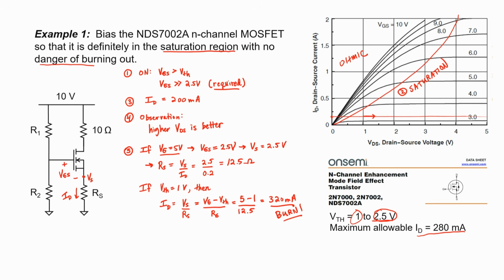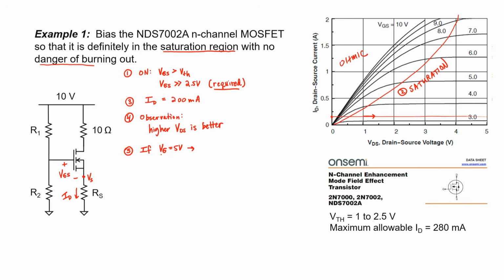Well, we started by assuming that the threshold voltage is 2.5 volts. Instead, we should have started by assuming that the threshold voltage was smaller and then checked the large case. Let's erase and rework it. Let's again start with a gate voltage of 5 volts, which I can very easily arrange by picking appropriate values for R1 and R2. For example, I could make them each a megaohm.